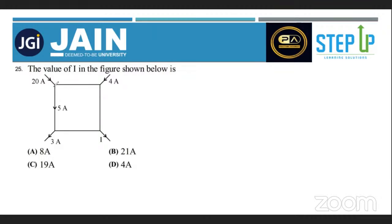See, obviously you can use the loop law of Kirchhoff. Whatever is coming out is going in. There's a long way also. Here 5 is going, so here 15 will go. Now from here, if 15 ampere is coming, total incoming current should be total outgoing current, so here 19 will come. Now here 5 is coming, 3A is going. So total incoming equals total outgoing, so 19 ampere. From here 5 is coming, 3 goes on this side.